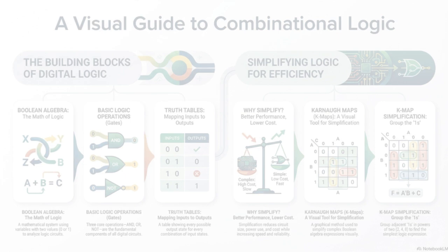You mentioned the BCD example earlier. That's a classic application. Perfect example. The BCD to 7-segment LED display decoder. The input is a 4-bit code for the number, say, 3. The decoder figures out exactly which 7 LED segments need to light up to display that digit. It translates code into physical action.